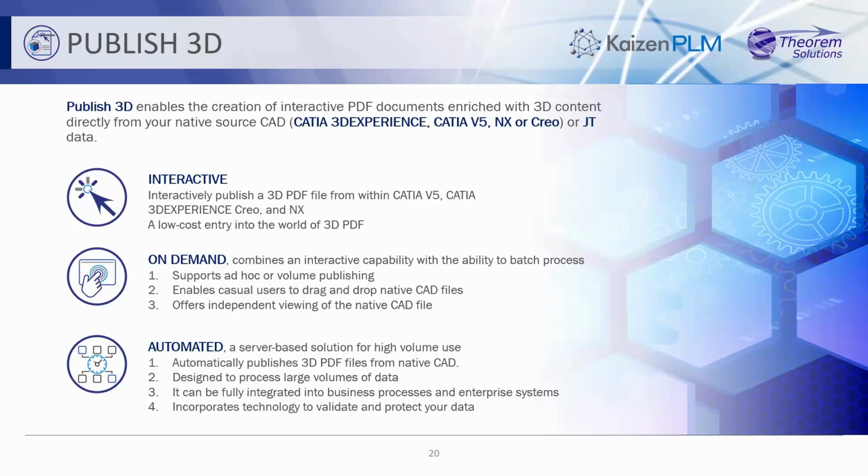An example of that is if you were a Teamcenter user. In the past, we've worked with a company to utilize 3D PDF using Dispatcher from inside Teamcenter. Dispatcher has the ability to run an external process, provided you can run it programmatically. So Dispatcher can run our software, create the 3D PDF, and save that 3D PDF back into Teamcenter.